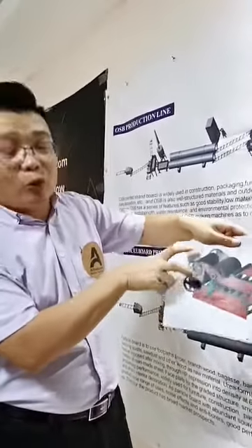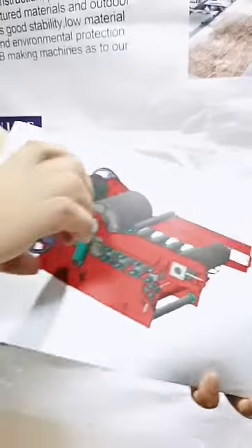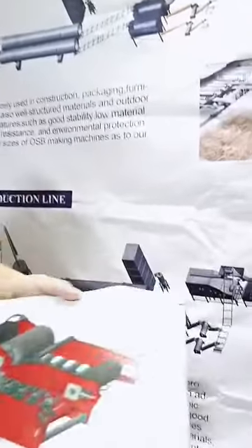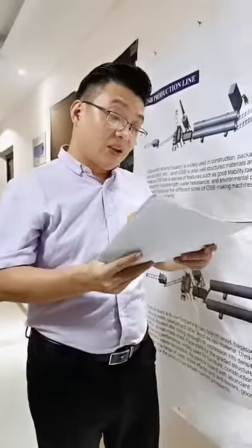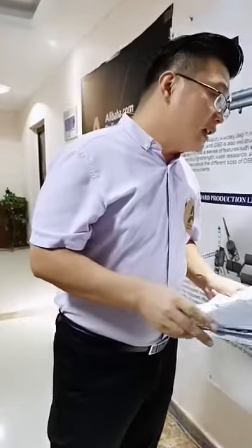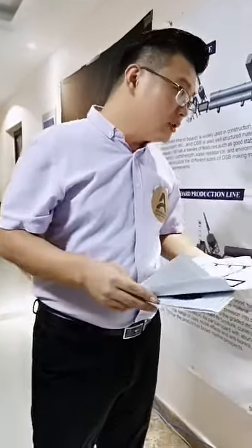The pre-press machine is a continuous, multi-roller one. At the beginning, it has 2 very big rollers, and the space is very big. In this press, the gap gets smaller and smaller: big, then narrow, then narrow here. Because after forming and felting, the particle board is very thick, maybe double or triple the finished thickness. After pre-press, it approaches the finished thickness.